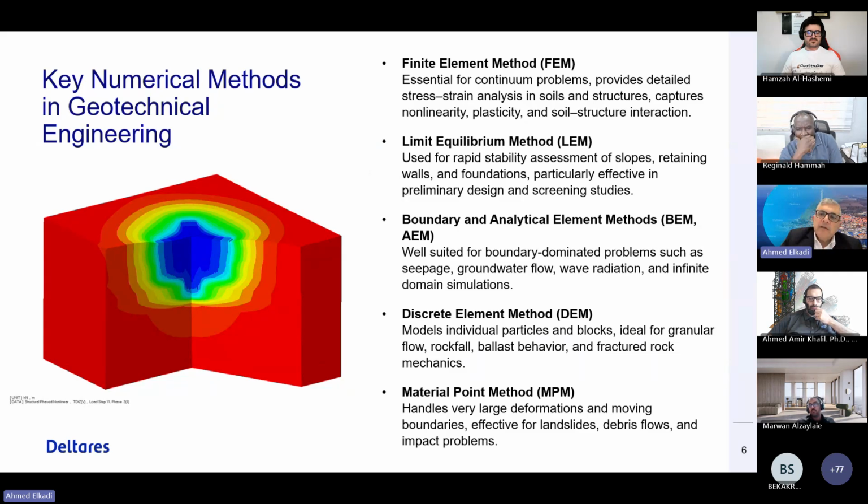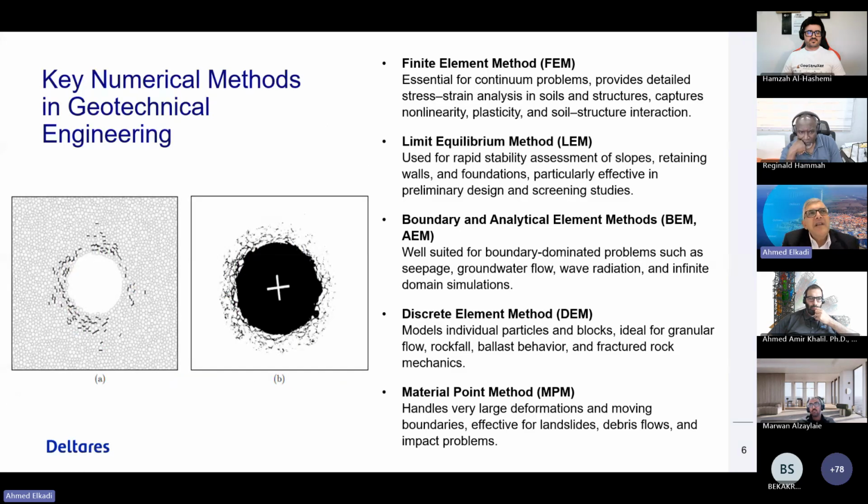Discrete element methods, and I had the opportunity to experience them in my PhD, where we can really model, let's say, discontinuities when we are dealing with particles or blocks, so fracture of rock, or in some cases concrete, can be captured very well. It is computationally heavy, as far as I can recall. Maybe there are new developments there, and also in the hardware, of course. But it's very valuable for certain mechanisms, certain problems, also coupled with maybe another solution.